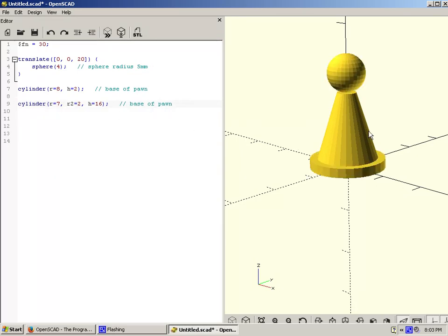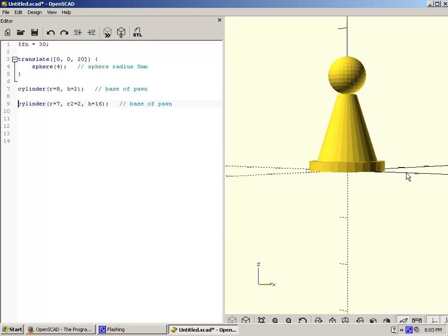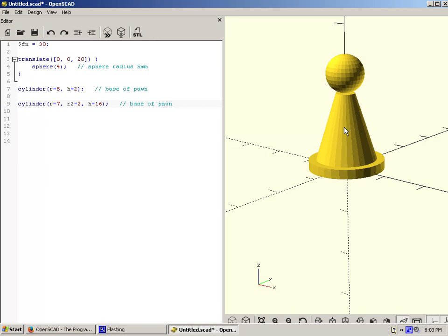You see here that the cylinder is touching the XY plane. We want to shift it upward a little bit, just for the sake of spacing things out. So I'm going to, again, copy this line of code for less typing. I selected this line of code, hit Control C, go down to here, and press Control V to paste it.